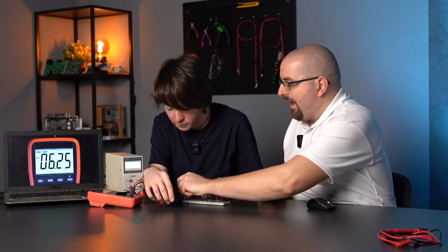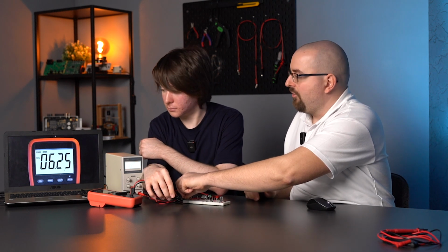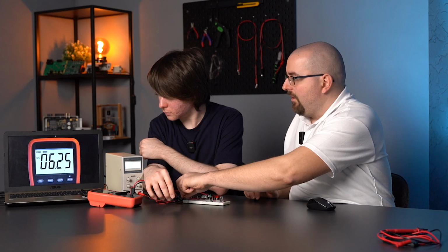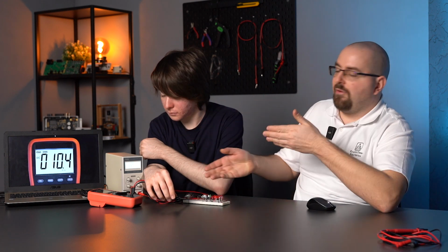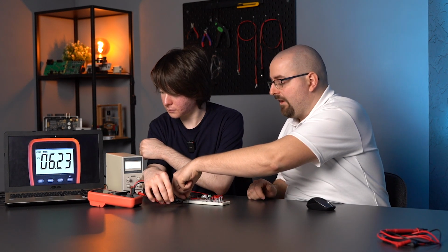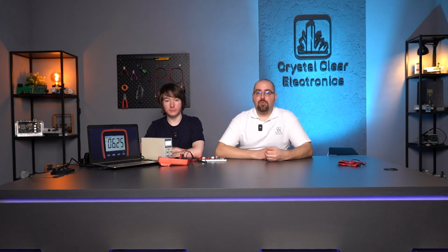Well then, the voltage is already here. I start to increase the load, that is to reduce the resistance value of the R2 potentiometer. Then you can see that initially we started from 6.25 volts and then I turn it around and increase the load current, so to speak, and suddenly we see that the voltage starts to drop a little and suddenly we are rapidly out of this stable state. I can reduce it to 0 volts once the potentiometer practically goes into a short circuit state. Okay, but obviously if I reduce the load, we get the 6.2 volts back. Usually, this critical current value is not stated in the datasheet as a minimum current, but as a recommended current.